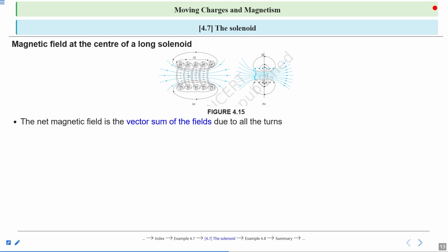You can see also the magnetic field lines are shown in the form of concentric circles, and the direction of magnetic field is shown anti-clockwise in the upper end of the winding in the A diagram. In the lower end of the windings, current is flowing perpendicular to the plane and inwards. So you point your thumb perpendicular to the plane and inwards and curl your fingers.